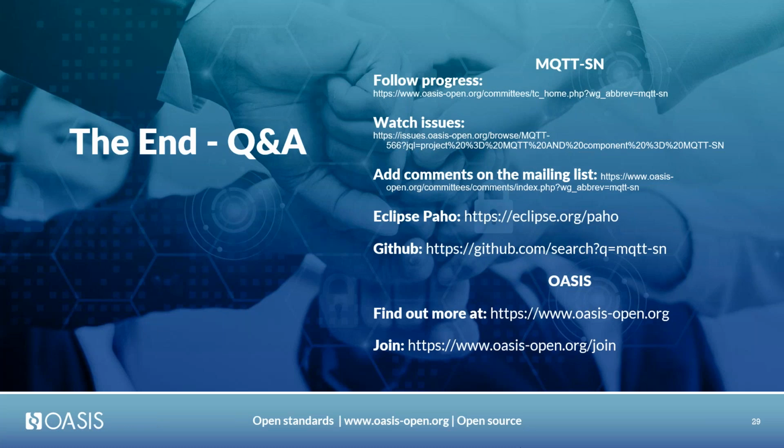But as Ian said, it's going to be via a gateway. Yeah, and this is a great point. I'm also not aware that any open source implementations are out there which can be used right now. So I think something like the u-blox gateway might be a good choice for doing this. And this is because, usually for other vendors, a standard MQTT-SN to MQTT gateway would be sufficient.